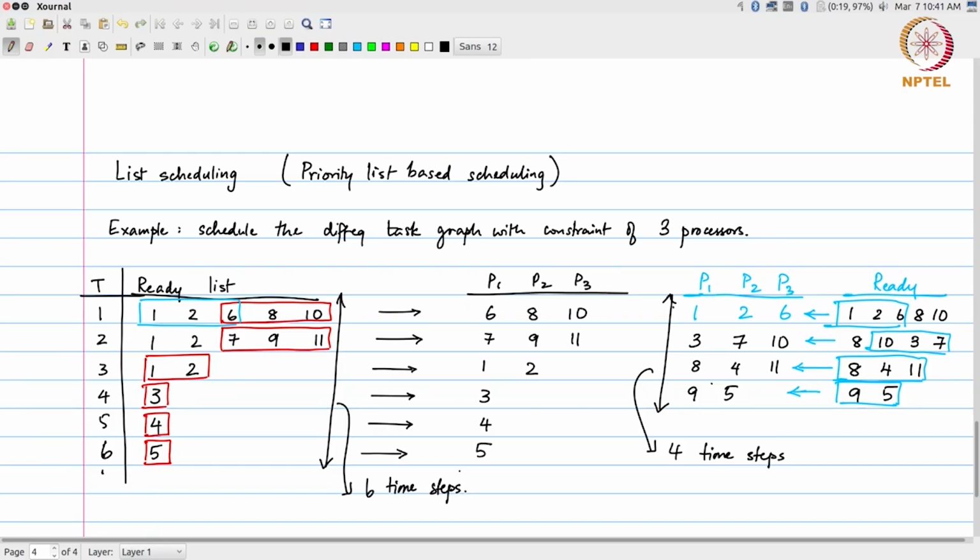Okay. If I wanted to do the opposite, which was latency constrained and then minimum resource, that is slightly more tricky, because basically what I will have to end up doing is try with a given set of resources, see whether I am able to meet the time latency constraint. If I can't, then maybe I have to change that latency constraint or change the number of resources, right, until eventually I am able to schedule everything within the constraint that I need. Okay. But there are heuristics that do that as well.